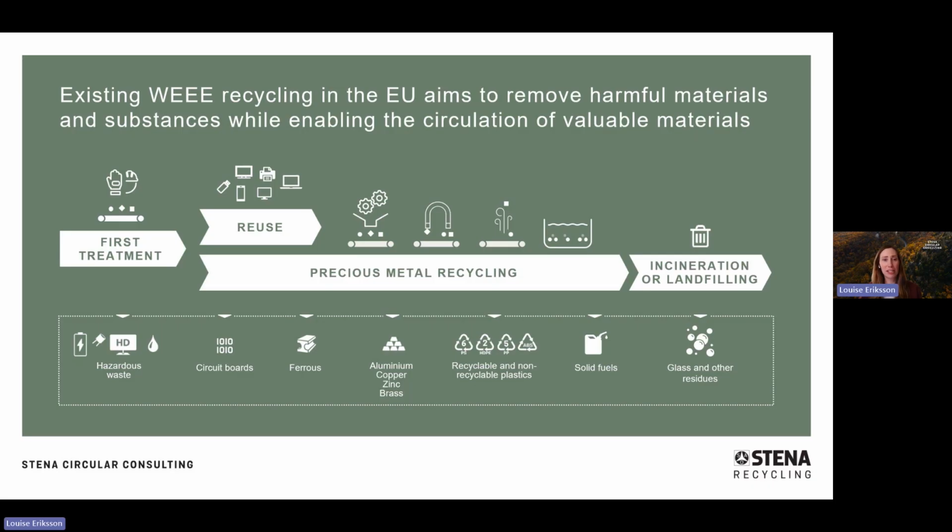And the PMR, precious metal recycling process, does not include any manual steps. So instead it consists of a series of roughly 30 steps using different technologies to separate and identify the materials that are there from each other, so to speak. So it's, for example, a shredder. The first step is a shredder to take down the products and the materials into smaller pieces, and then magnets, eddy current magnets, sieves and sink and float pads, etc., are separating these materials into different fractions.